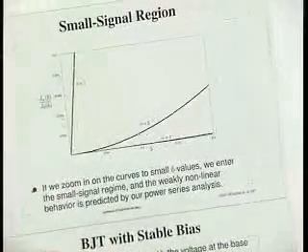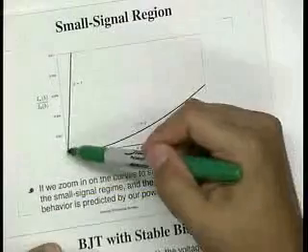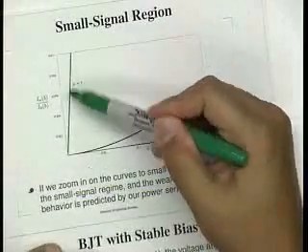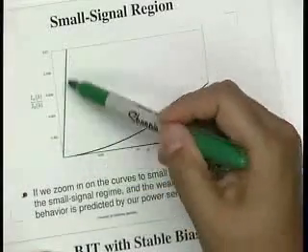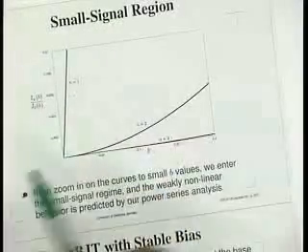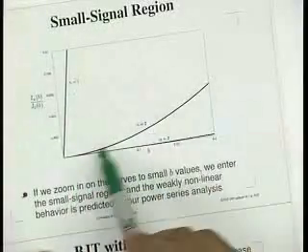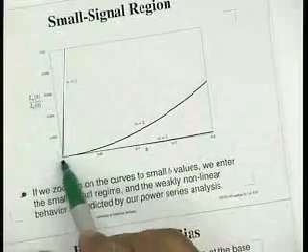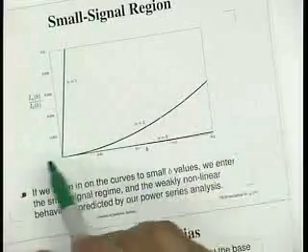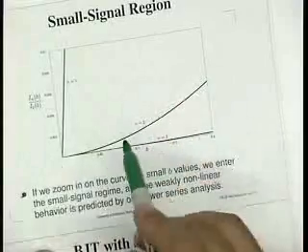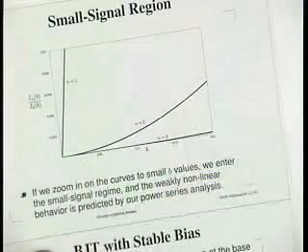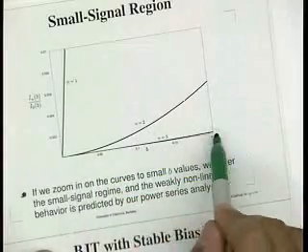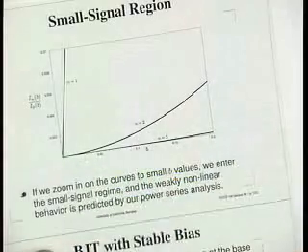So this is zooming in, and you can see that this is a nice linear line. It's telling me that as I increase the input power, the output power is increasing in step. And this is how much the second order is increasing, right? For very small signals, this should increase roughly like x squared, or b squared. And so at very small values, I would expect this to be parabolic. And this should be like x cubed or b cubed, and so on and so forth.